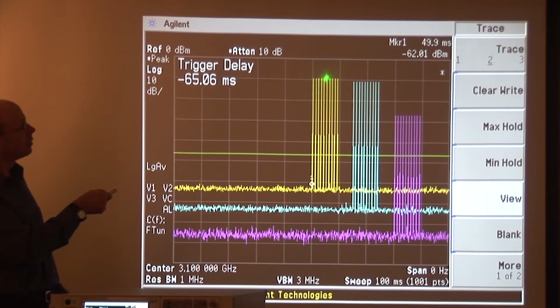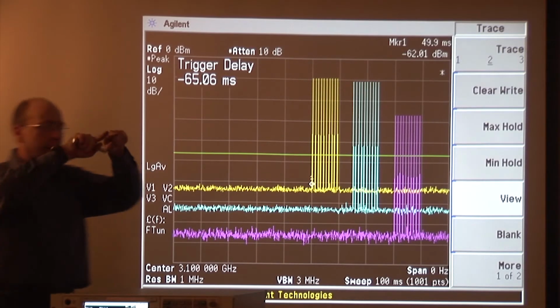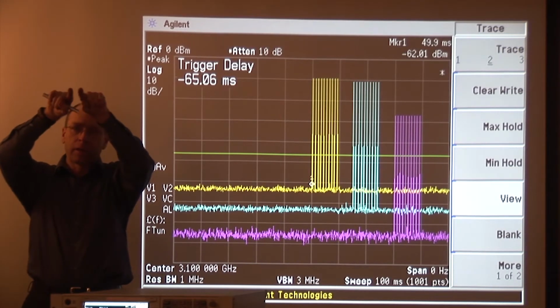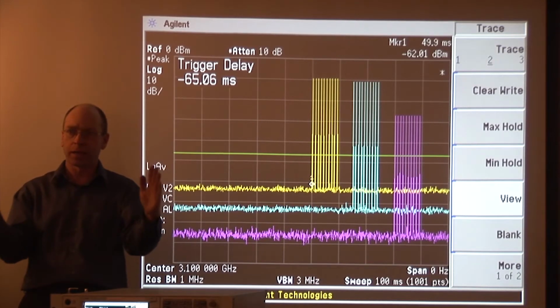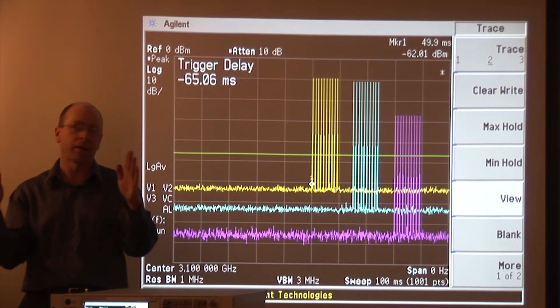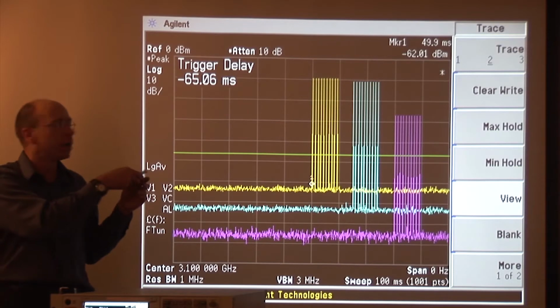Yeah, this is due to the slight difference in the way that the 8 megahertz wide filter is not only getting all the power in the fundamental lobe of that spectrum, but it's getting a little bit of power off in those side lobes off to the two sides. It's not much of a power contribution, but there's a little extra power, and that results in that small delta tick right there.